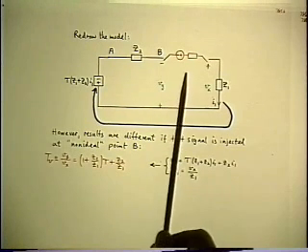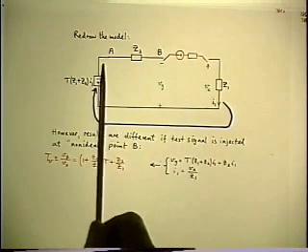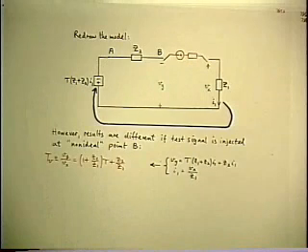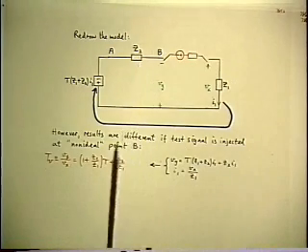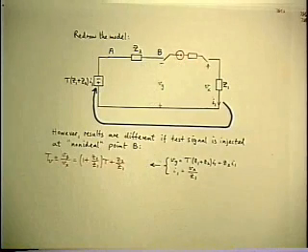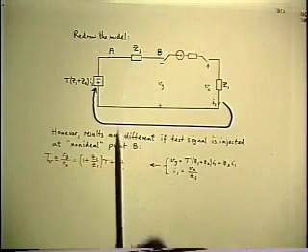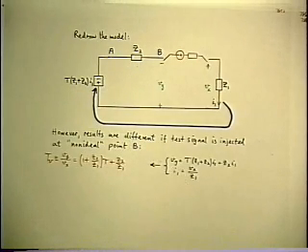So you get the wrong answer for measuring Vy over Vx if you can't get to an ideal injection point. But it's certainly worthwhile doing this, because now we know what it is we do get. And obviously, if Z2 goes to 0, then it reduces to the right answer because you're reducing it back to the ideal case again. But if it's not ideal, it tells you how small the Z2 has to be in order to get close enough to the right answer.